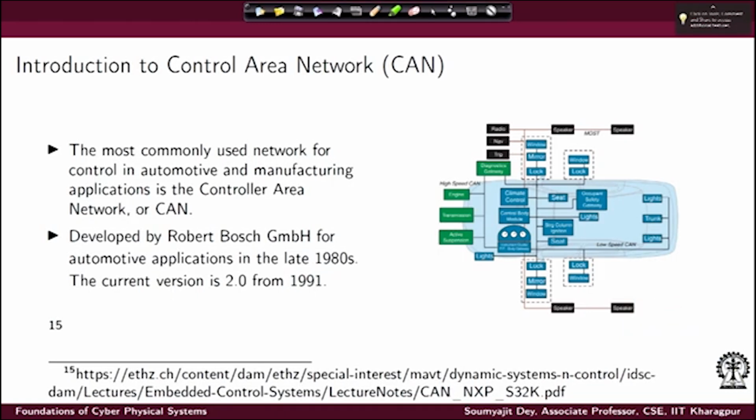So essentially you need to have a very simple network protocol, some protocol which doesn't require too much network infrastructure, lots of switches, nothing like that, because this would be inside a car and it should be as low cost as possible, right? So in this way, the most commonly used protocol that we have in automotives is called Controller Area Network, or CAN bus, okay?